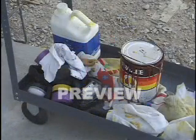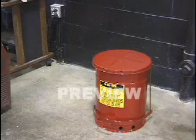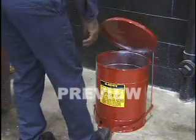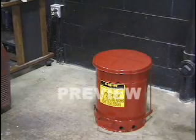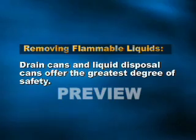Oily solvent-soaked rags can easily start a fire through spontaneous combustion. To prevent this, specially designed waste cans should always be used for temporary storage. These cans can have spring-loaded lids and a raised bottom with vent holes to dispense heat. For removing flammable liquids from the workstation for disposal, drain cans and liquid disposal cans offer the greatest degree of safety.